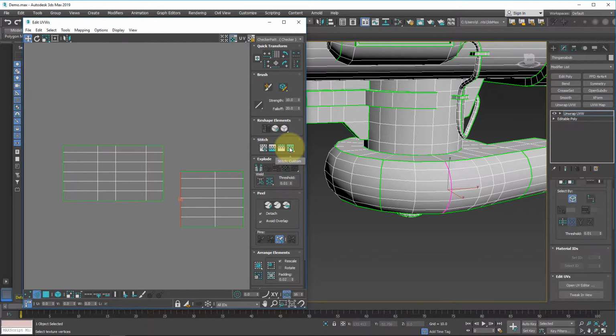If you click on that, it will actually move a UV island to match. So if I click here with my edges selected, it will move that other island to stitch there, and we don't get any weird distortion when it averages the 2 edges in between. Also note while stitching, edges work best. Just be sure to choose all the seam edges you want to stitch, as the tool will only connect the edges in your selection.